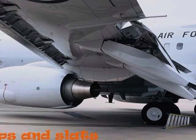Three factors which affect the generation of lift from a wing are the curvature of the wing, the area of the wing, and the speed of the air which blows around the wing. Since during takeoff and landing we have lesser speed of the air particles which flow around the wing, in these two regimes of the flight we need the wing to produce more lift at lesser speed. How can we do this? It is possible to increase the surface and the curvature of the wing by movable surfaces that are installed in the leading edge and in the trailing edge of the wing.